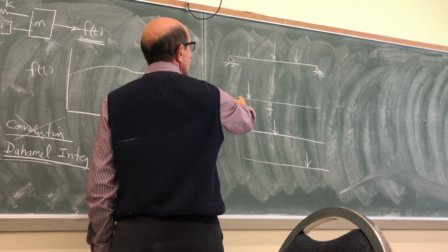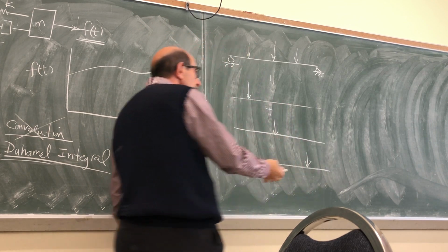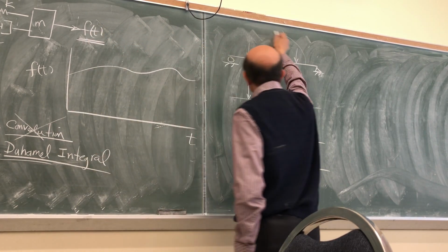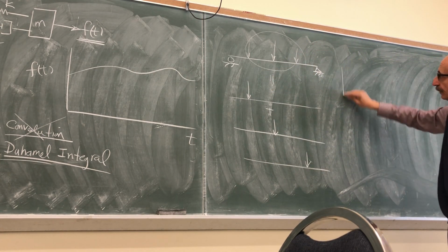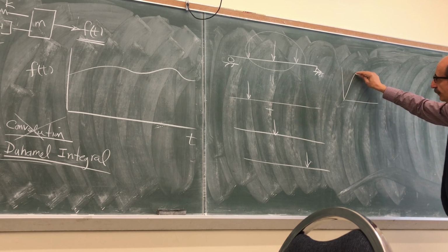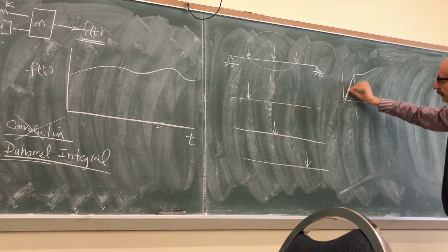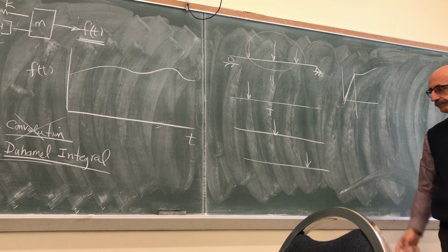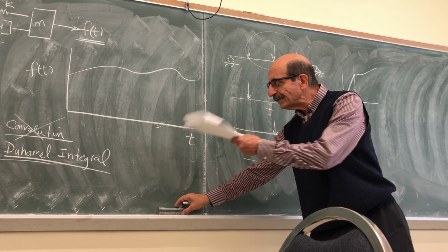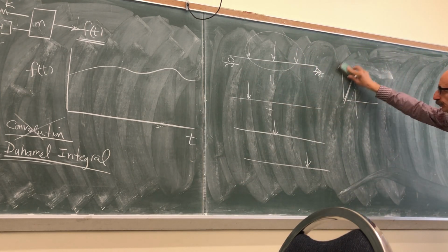If you find the moment diagram for this case, and this case, and add them up, that would be the moment diagram under the action of all of these. All of this is because the system is linear, so as long as you have a linear system, that is, the material is within this range, the responses just add up. So that's the basic concept behind the Duhamel integral that we are going to use. And what is that?